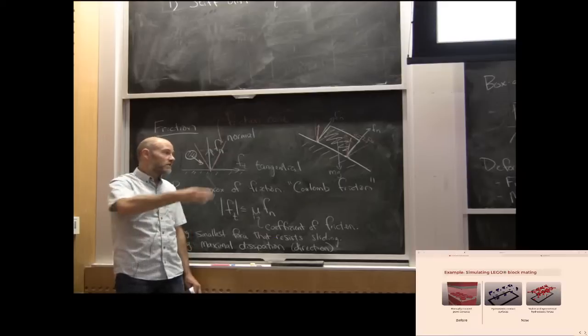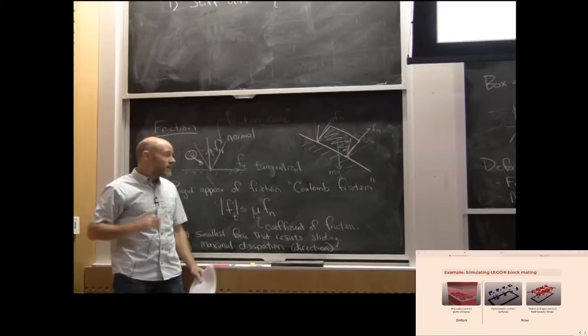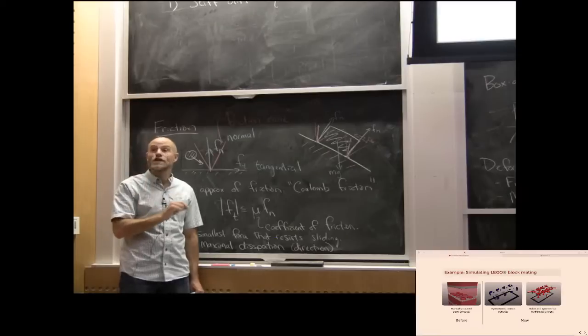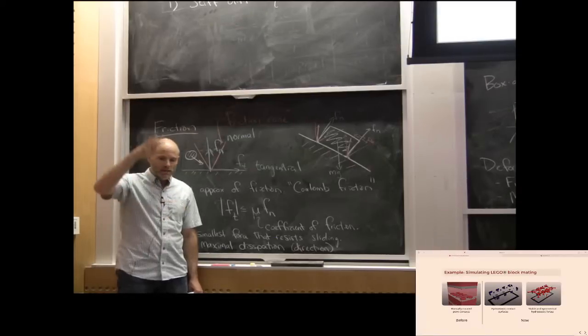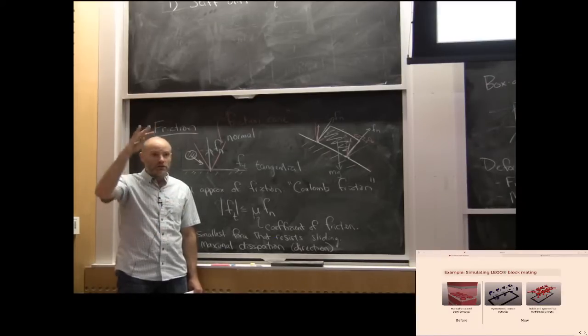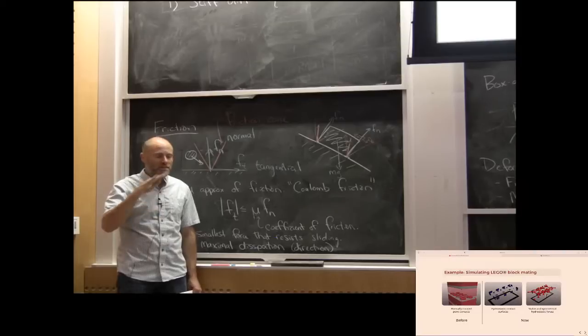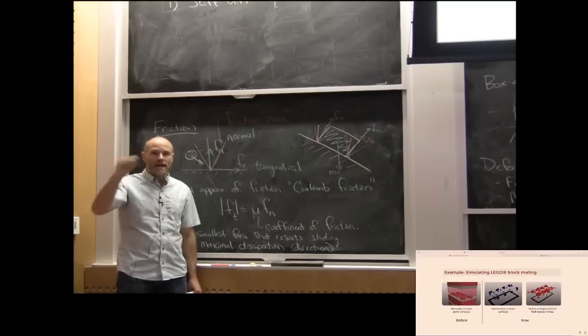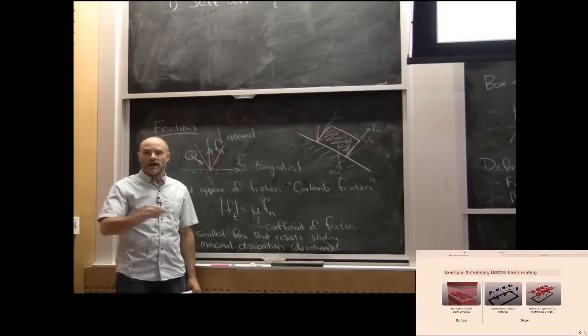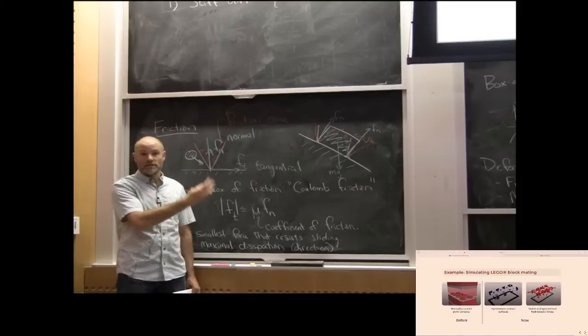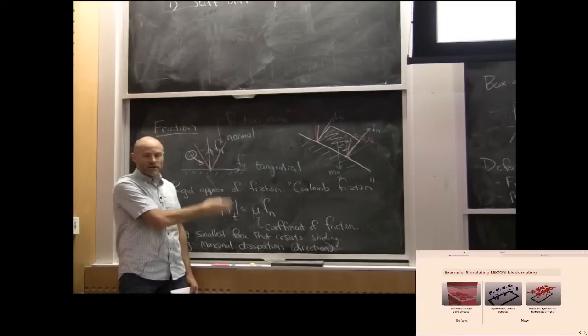What makes a fast simulator is really how big you can make h. There's a little bit about how much you've optimized your multi-body code, but the dominant factor is how big of a time step you can take, and that's a property of your integrator and your equations of motion.